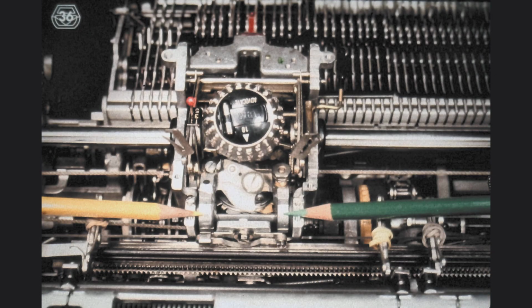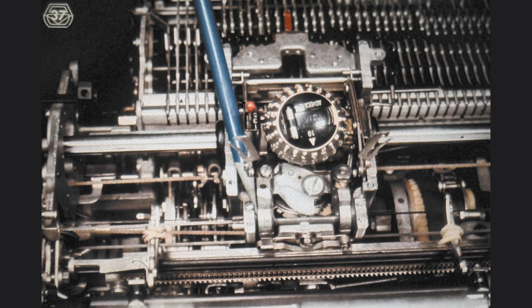Our second adjustment in the sequence of adjustments needed for the alignment of the characters is that of the end play of the rocker. The 2 points indicated by the yellow and green pencils show the location of the pivot bearings for the rocker. It is necessary that the rocker be allowed to rotate with minimum or absolutely no side play. If you closely examine the space on the right side of the rocker, between the carrier and the rocker, you will find a retainer that limits the lateral play of the rocker. Investigate this on your machine and be sure to locate the retainer.